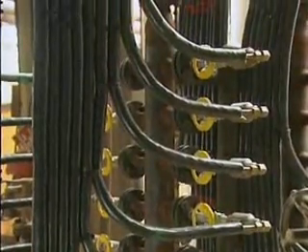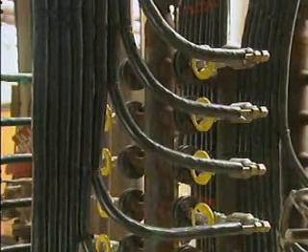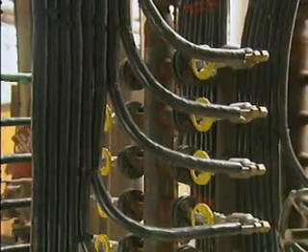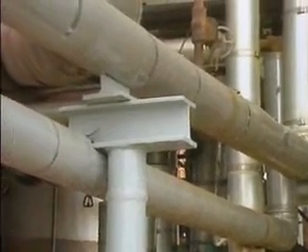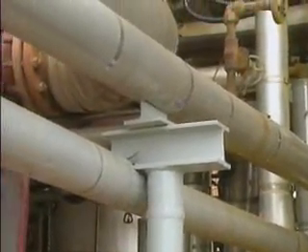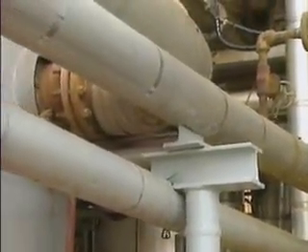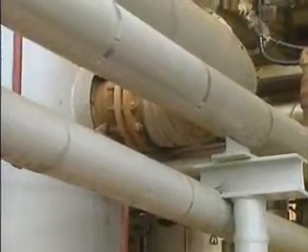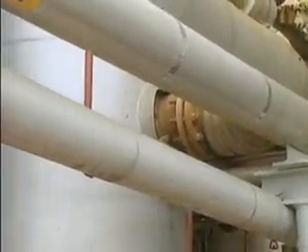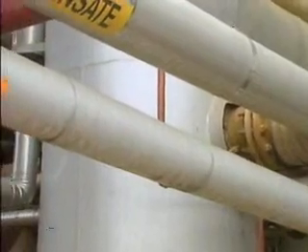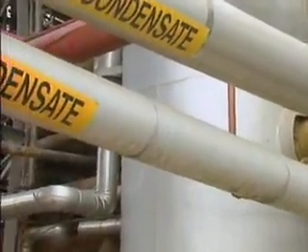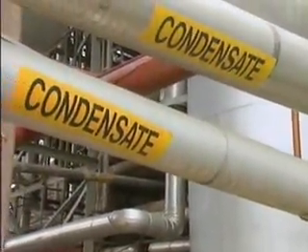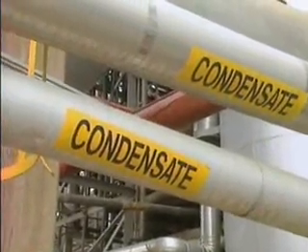So a temperature inspection alone probably won't give reliable information about the condition of a specific trap. On the other hand, in piping systems that have sufficiently large return piping, a failed trap may cause no rise in back pressure, and the temperature differential would remain unchanged. So this is another situation in which measuring the temperature differential across the trap won't detect the trap failure.